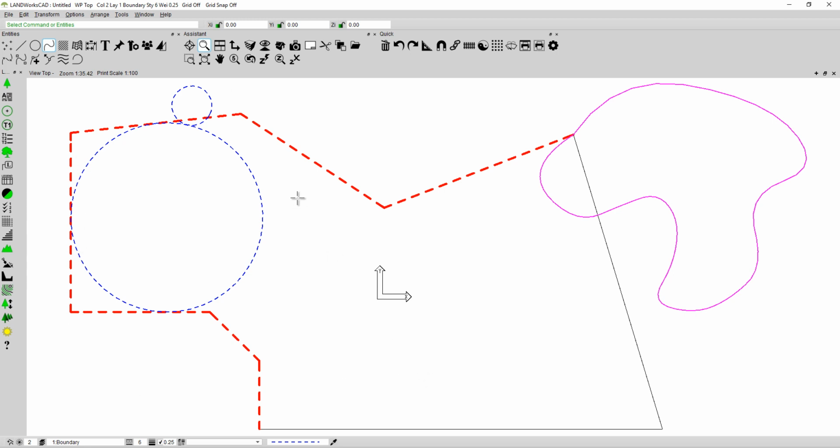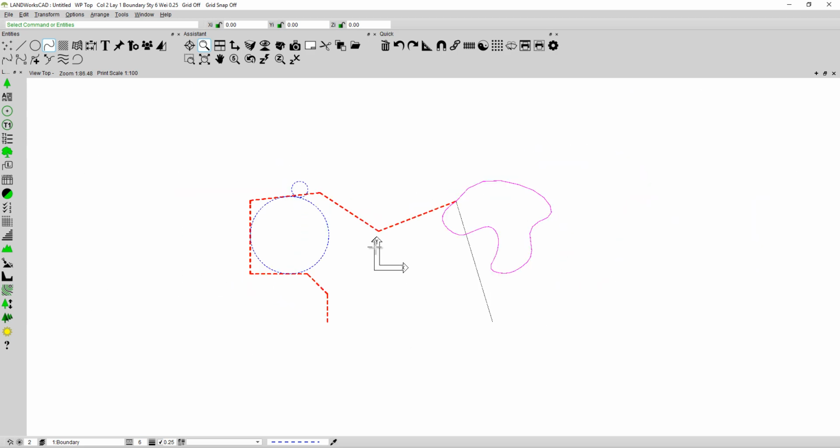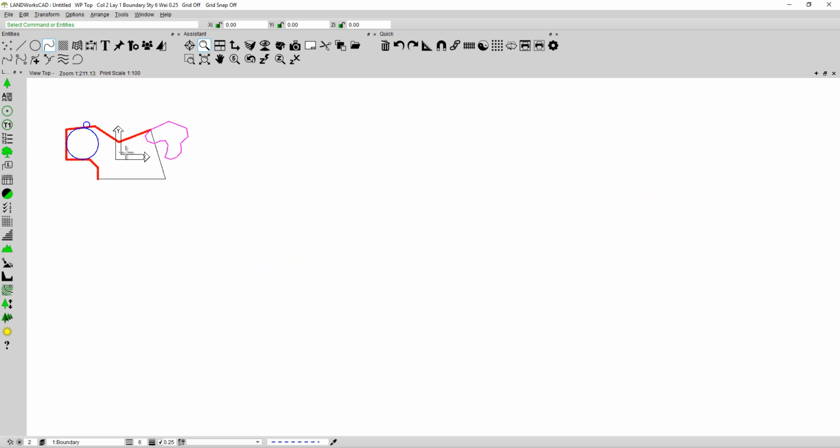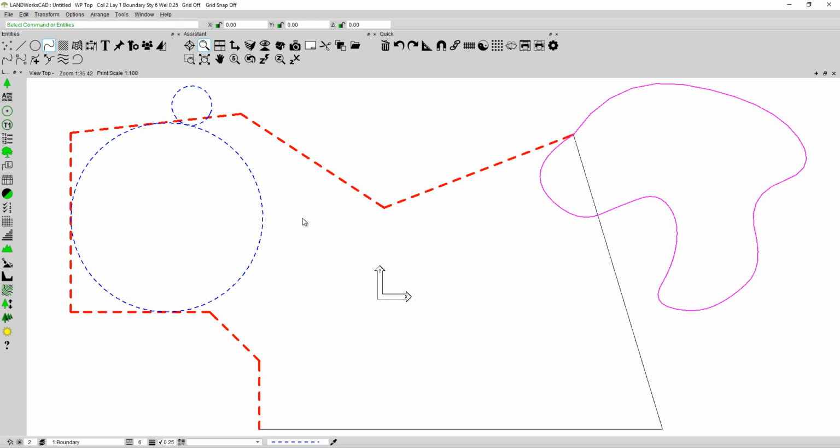There is a particular shortcut for this same command, which I'll share with you now. If I wanted to zoom fit, but I didn't really want to have to come up here to do it, I can simply hold my cursor anywhere I like and double click on the mouse wheel. That double click action is exactly the same as me selecting this command.